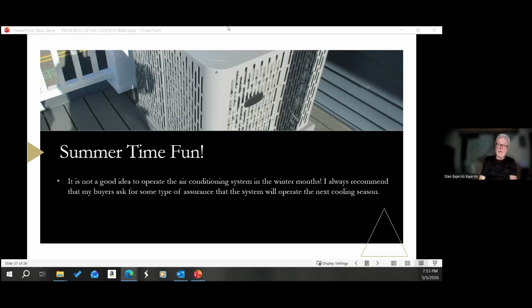But guys don't do heat load calculations anymore. They put in what's there. They just duplicate what's there. In a lot of older houses, they were oversized anyway, especially heat. So you can't determine the heat load without doing a heat load calculation. We used to do them by hand with a calculator. Today, they're in a program. They're much easier to do.